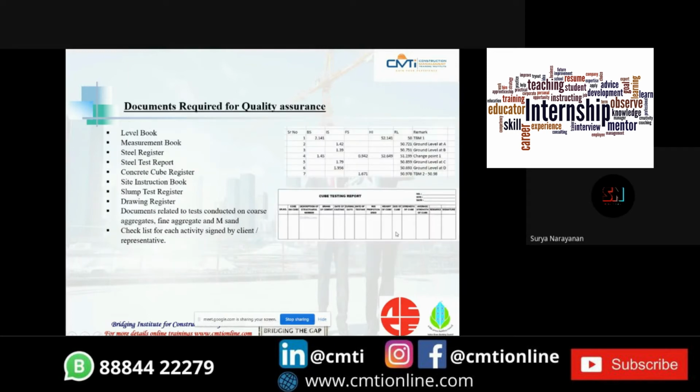So, documents required for quality assurance. These are the documents required: a level book, measurement book, steel register, steel test report, concrete cube register, site instruction book, slump test register, drawing register, documents related to tests conducted on coarse or fine aggregates, and a checklist for each activity signed by the client or representative. These are some examples which I have given in pictorial representation.